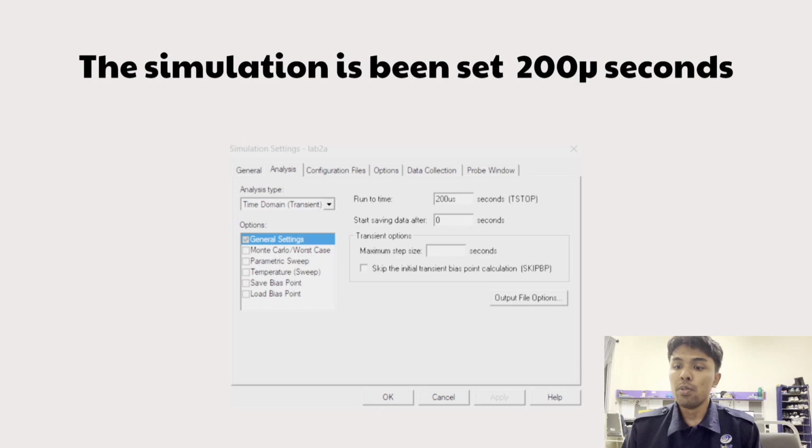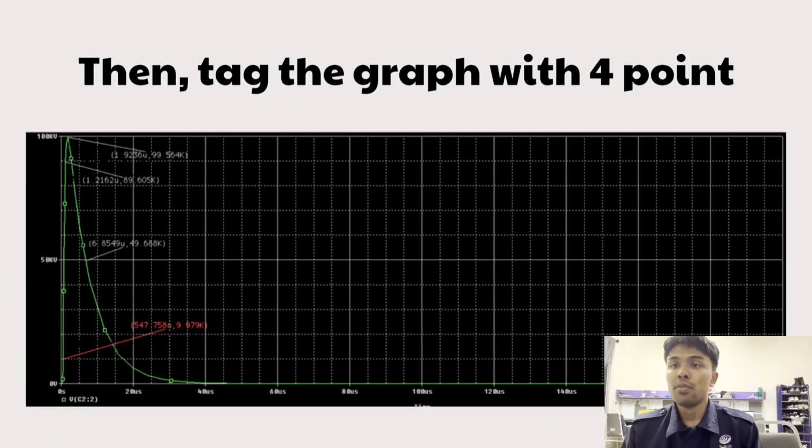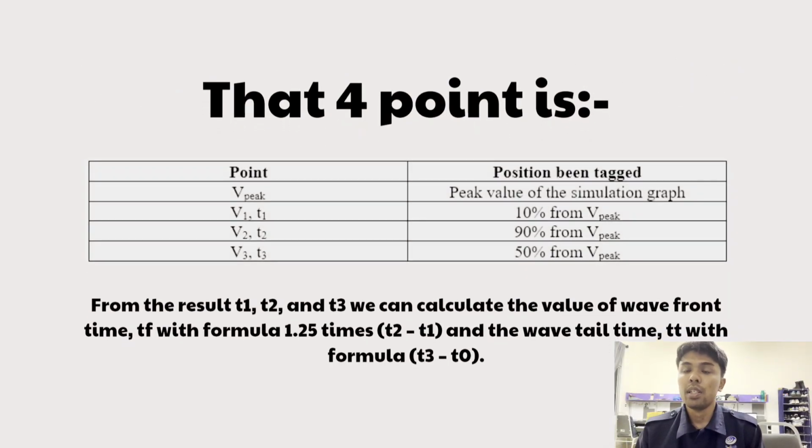After we click run, we will wait for a few seconds, and then the graph will show up. When the graph shows up, we will take 4 points on the graph. The first one is V peak, that is the peak value of the simulation graph that we get. The second one is V1, which is 10% of V peak. The next one is V2, 90% of V peak. And V3 is 50% of V peak.